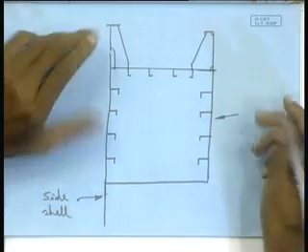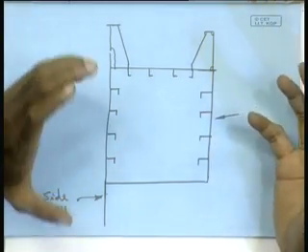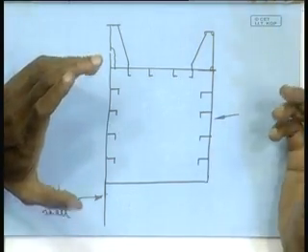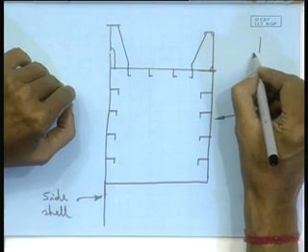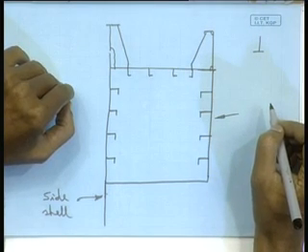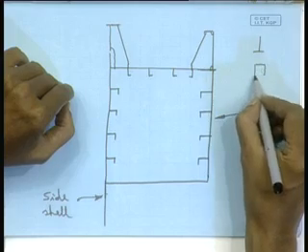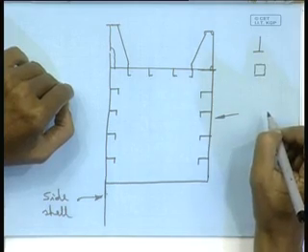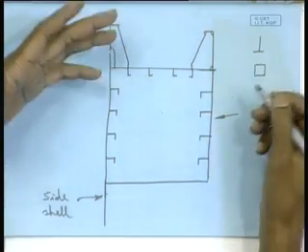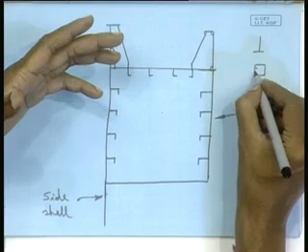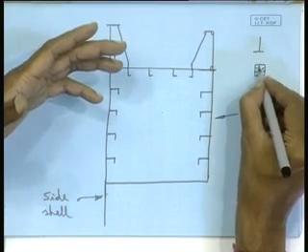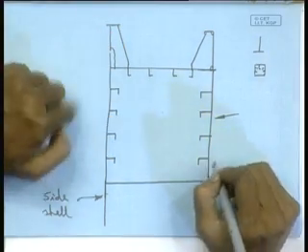The word girder means essentially a heavy stiffening member. That girder can be just a T section, right, or girder can be a box like a thing. In this case, it is not only a box, it is a stiffened box. It has all kinds of stiffness inside, right, like we can see.